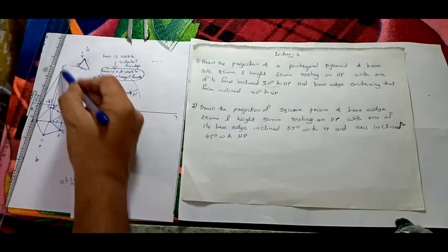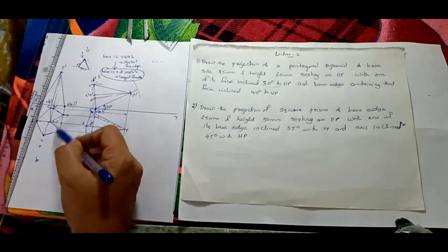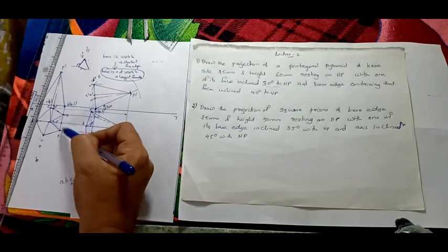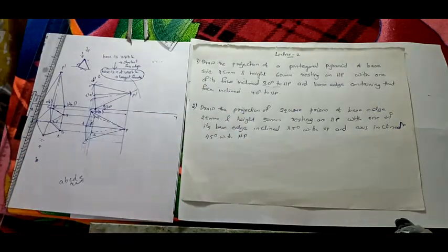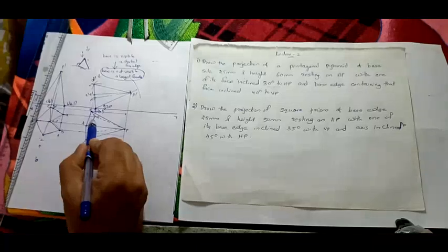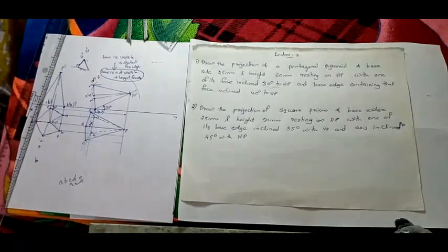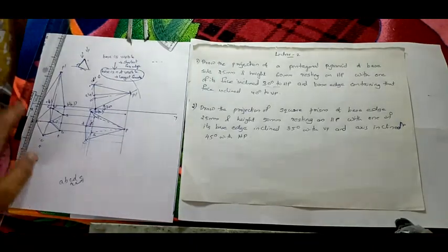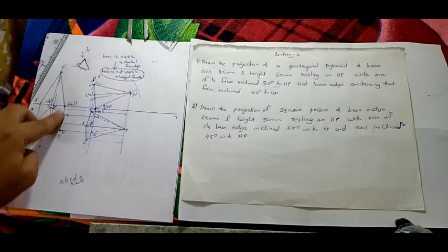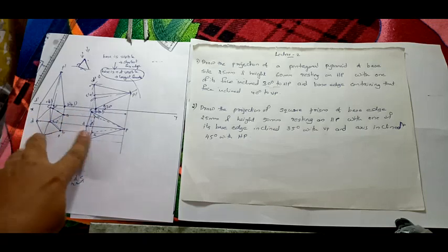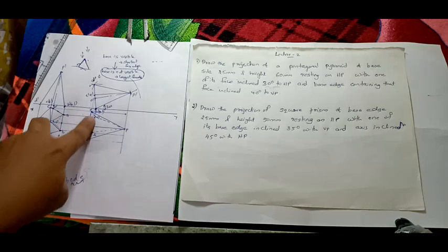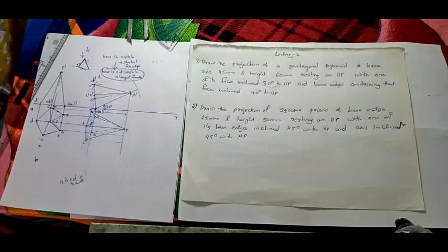So the face edge on that line, AB, is the face edge on that line, right? So that face edge should be inclined 40 degree to VP. Before drawing that, you have to check whether true length is visible or not. Simply you can tell. See, actually this is 25 mm, right? This is 25 mm, that is true length itself. True length we have drawn here. If we draw two parallel lines like this, this AB will also measure 25. So that is true length, right?